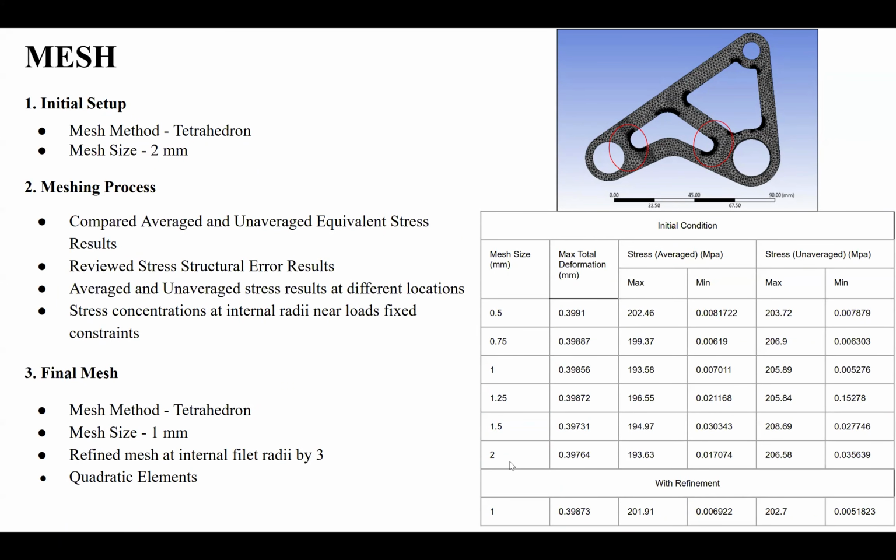size of 0.25 millimeters. During the process, we found that the initial geometry had sharp edges where max stresses were located and caused singularities. To avoid this, we slightly altered the geometry by increasing the chamfer to not interfere with the edge of the fillet radius.